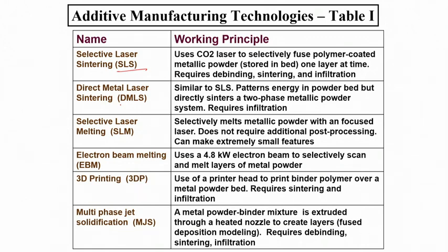When you heat, these binders melt, fuse, and bond with each other. In one case you have two particles with a certain coating on top, and the coating fuses easily and binds. On the other hand, in direct metal laser sintering, you have two metal powders and they can fuse by a typical welding process.